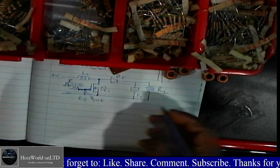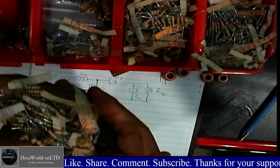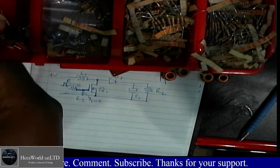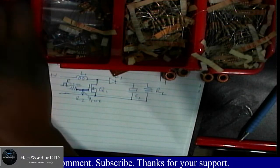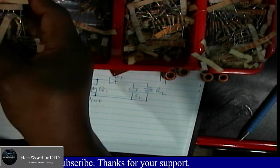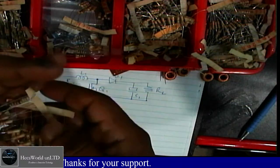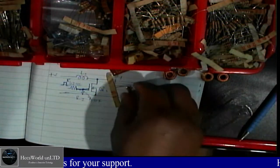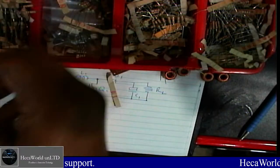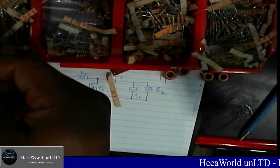Now if you don't know how to find the value of a resistor, you can go to our basic electronics tutorial to learn how to find the color codes of a resistor. Now this 10K doesn't have to be exactly 10K. We don't have to spend so much time looking for it. We can use another value higher than 10K, which should be fine as well.